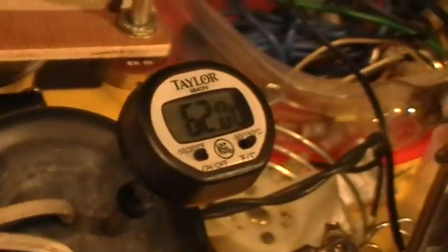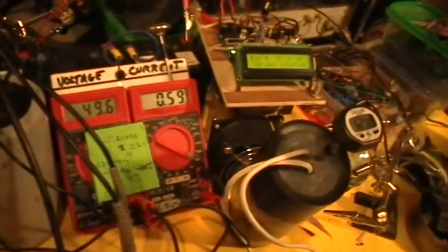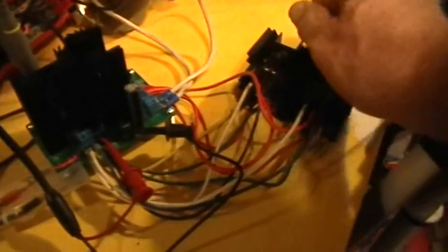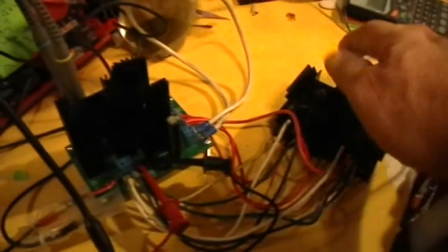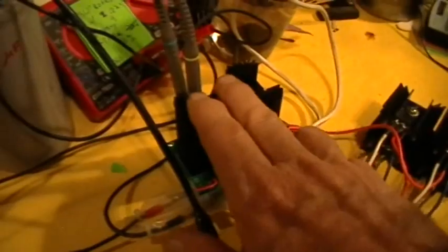Getting a good rise over ambient there. But of course most of that is coming from the Q1 on times, I believe. Oh, the MOSFET temperatures. The Q2s, the 4 Q2s, are perceptibly warm. So they're being swung through their linear operation region, which means they are dissipating more power than they would if they were switching cleanly. The Q1, which is switching fairly cleanly, is slightly warm, but not as warm as the Q2s. The current sense resistor, of course, is cold.